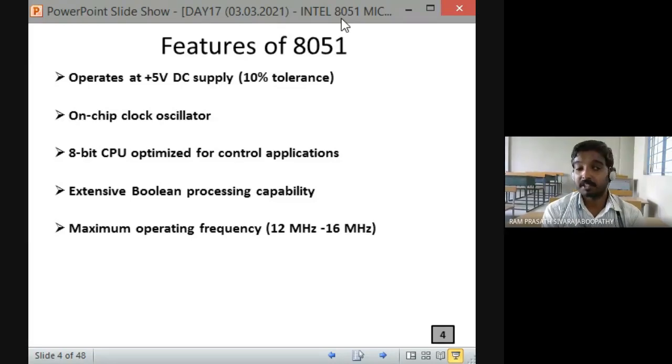So when we talk about memory, there are two ways you have to see it. See, I am giving a task to the microcontroller. That is a program. It must be stored permanently. Once I have written the program into the microcontroller, till I reprogram it, it should function according to the code I have written. So definitely it needs ROM memory, which is read-only memory. So it is non-volatile memory. Correct or not? Once you store the program, it will be available till you reprogram it.